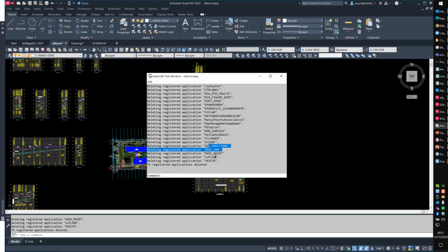So, and then SDI and SDKs. That means something in this drawing, or an XREF that had been brought into this drawing, was originally done in MicroStation, Carlson, or Eagle Point, or had those applications used in it, and has now put those things in here, and we want to make sure we strip them out. This is why that minus purge is so important, and purging reg apps regularly. And then again, we talk about the XREF